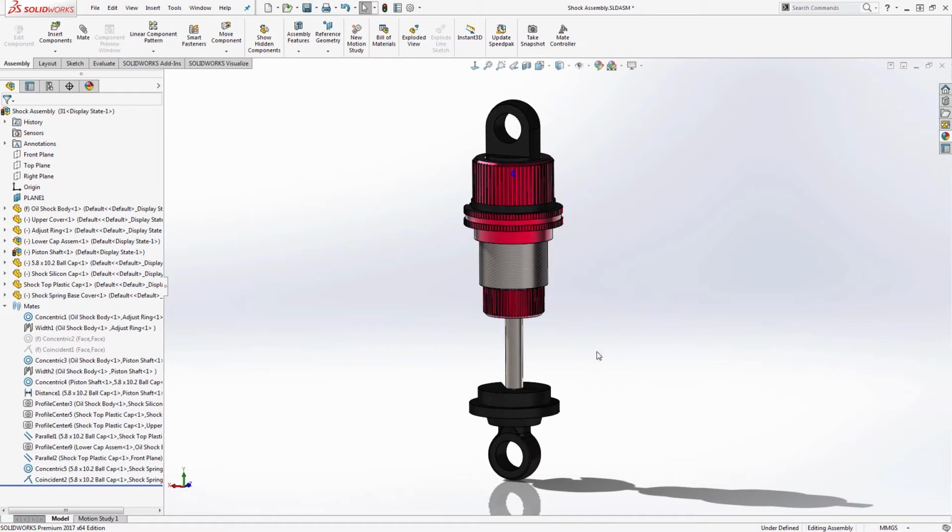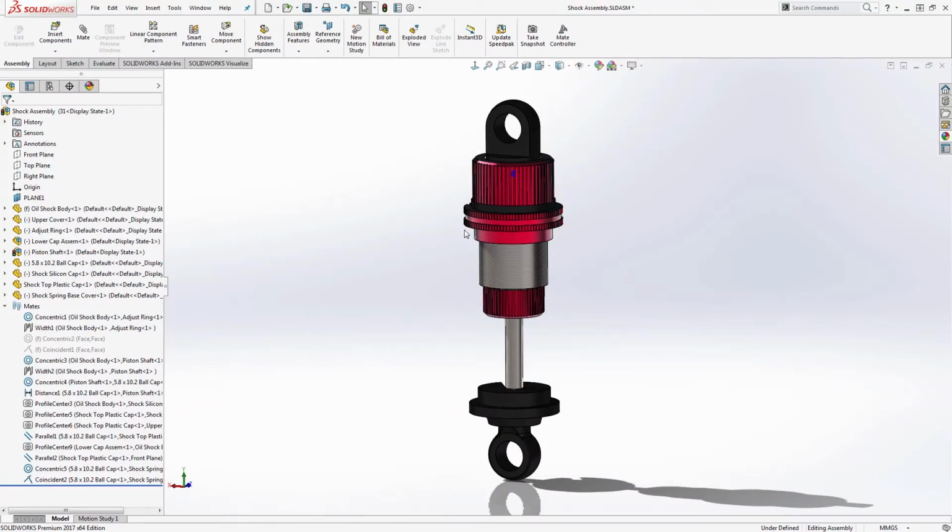Now the way that this animation works is to trick the SOLIDWORKS animation into acting like the spring is actually compressing. Of course, we don't have any actual deformation or any kind of mesh techniques that we can use in animation. But what we're doing is creating some geometry that will update on a frame-by-frame basis as it gets into the animation and look like the spring is actually compressing. So again, what we'll be doing here is creating a set of bounds up here and down here that will follow the locations of the components from within the assembly, and those will then slide up and down as we're driving them with the mate, which will drive the component, in this case our spring, in the middle.